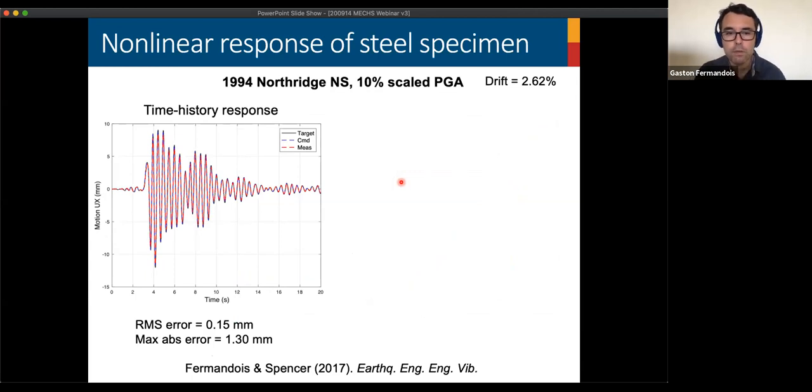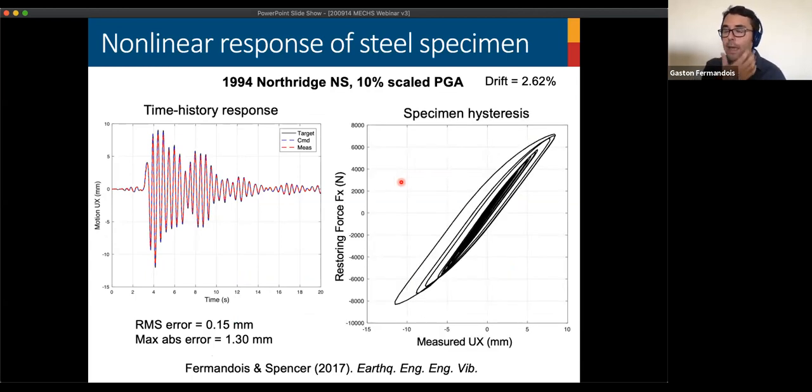And in this case, we also ran the test with a nonlinear behavior for the steel column. So this approach also accommodates nonlinearity on the specimen. I can tell you that in the case of nonlinear behavior with a softening phenomenon, it's a good situation, because it means that the interaction with the specimen and the actuators is softened, and less specimen interaction means that the system will behave better. So this is not a problem to deal with.